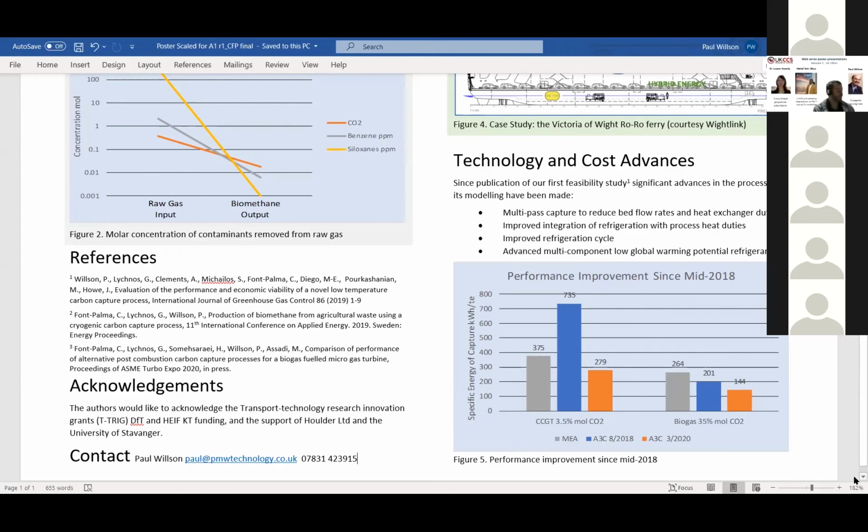While everyone else is thinking about the questions, I've got actually 3 questions, and I think that should be rather quick fire for you. When you say you've got a mixed component refrigerant cycle, I assume it's a mixed Joule-Thomson refrigerant cycle? It's a conventional evaporation, compression, condensation, evaporation, refrigeration cycle. It's unusual in the way that it rejects heat, but that's the only thing that's unusual about it otherwise.